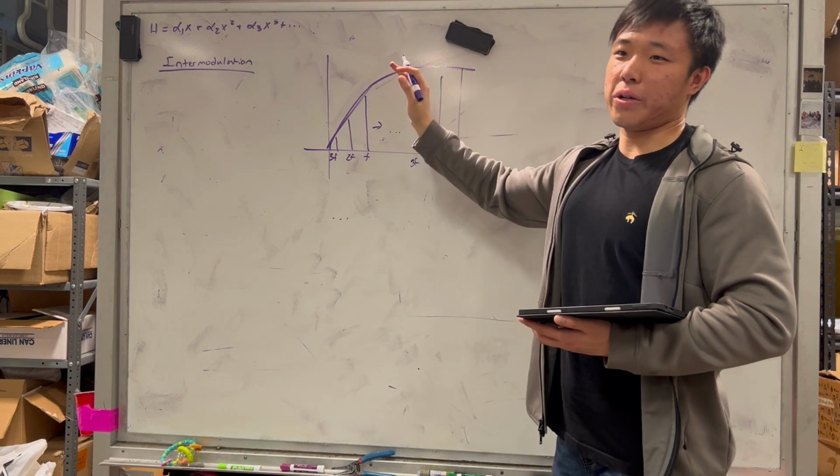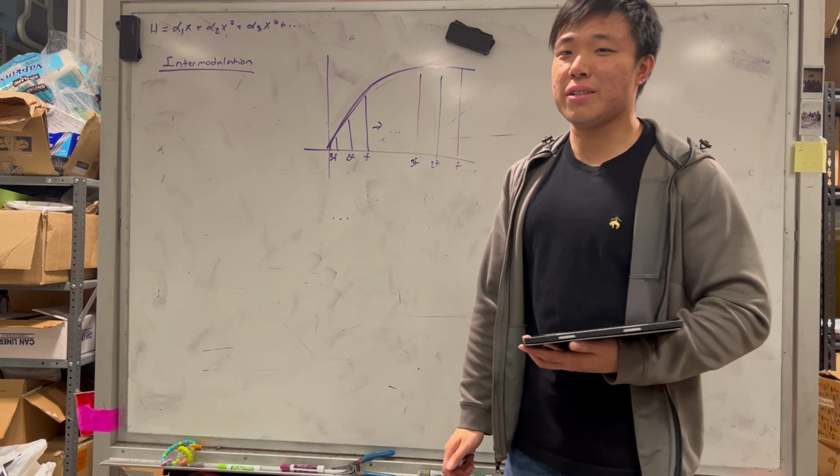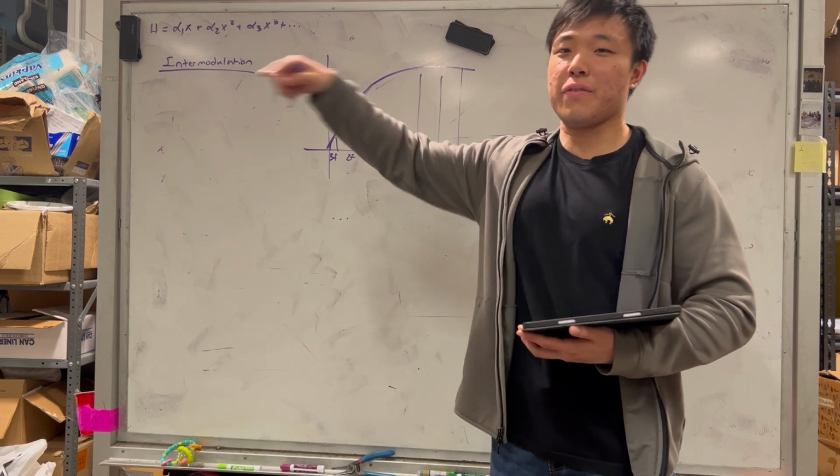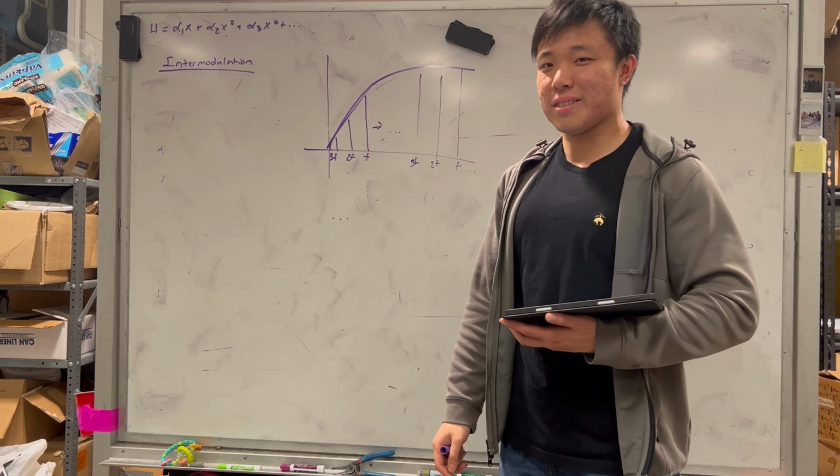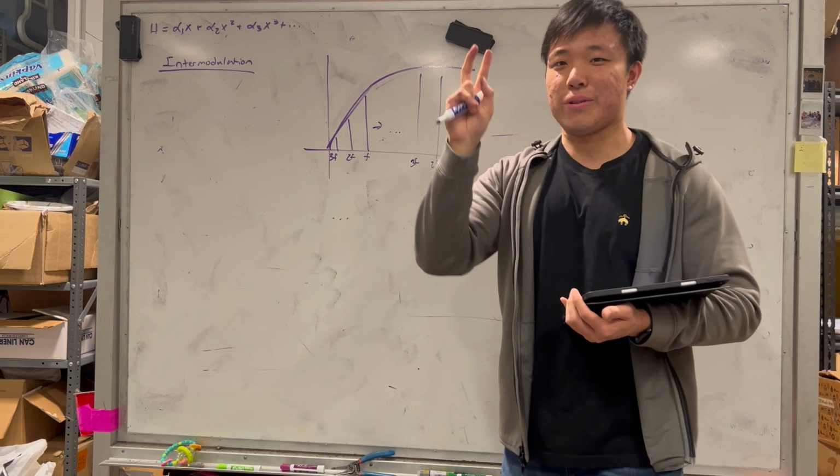That means they're all going to experience a similar amount of amplification, and therefore you'll see all three of the harmonics at relatively the same strength in your output signal. That's what's meant by total harmonic distortion.